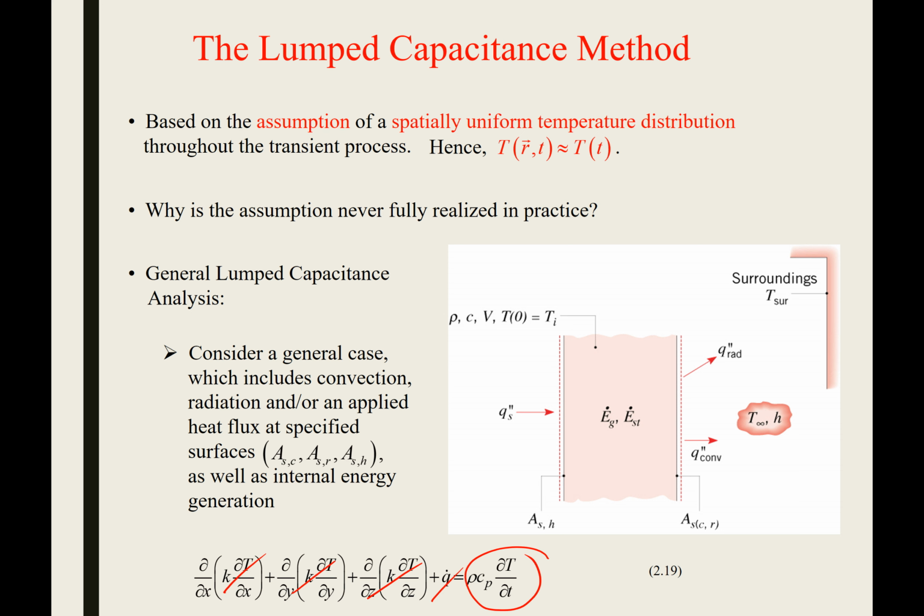So last Friday, we started on this topic of transient conduction. So who can explain what the word transient means? Okay, yeah, changing, or in mathematical terms, we do not neglect the accumulation term in the heat equation. So we have to account for how things are changing, and specifically this term helps us track how our temperatures are changing with time, and really how energy is being stored with time.